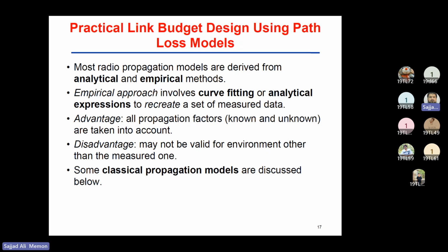Before that, we should have calculations of what will be the power received by the receiver antenna if we transmit this power and consider all the losses that may occur in the channel. Then you will know whether the power received by the receiving antenna is sufficient, whether it is greater than, equal to, or less than the minimum power. If it is greater than the minimum power, then it's okay, no need to improve further.